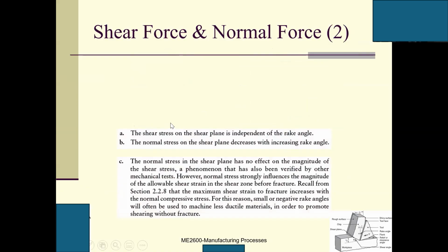So there are some observations. The shear stress on the shear plane is independent of the rake angle. The normal stress on the shear plane decreases with increasing rake angle.